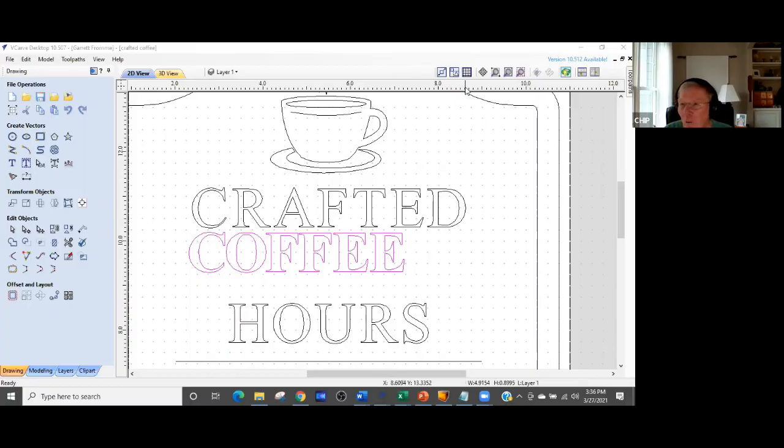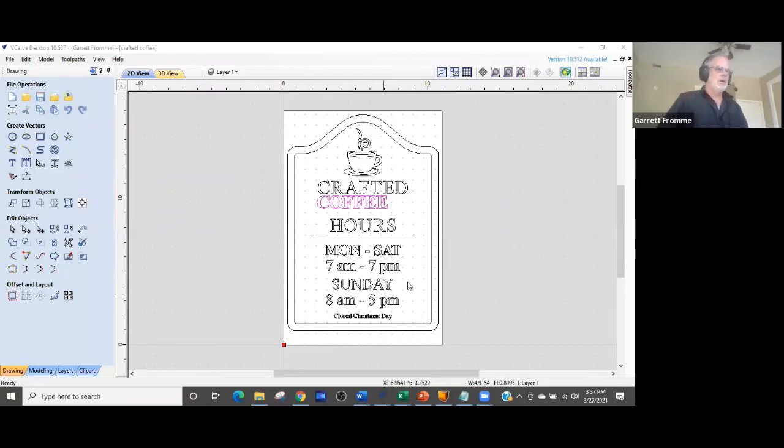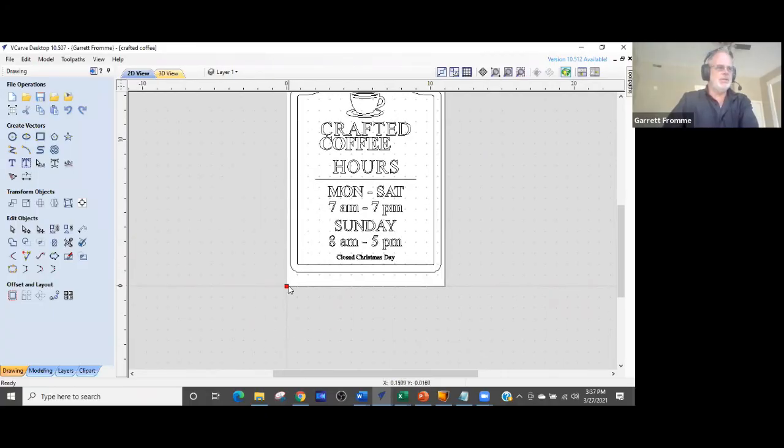And the other question I have is, almost everybody's drawings start with the center of the project. But then when they start setting up the tool path, they move to the lower left-hand corner. Why? Because it's easier to find the corner than it is the center of the material. So we are looking at this project here, and this board, let's just say it's 12 by 16. It's a lot easier to eyeball the router bit down to this corner here than it is to find your exact center on your board.